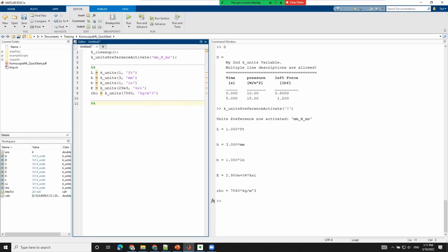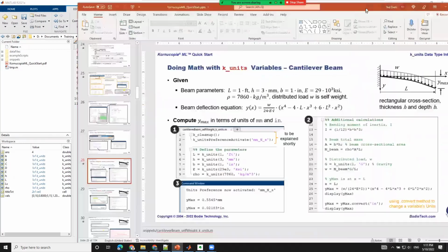So in the formulation of the beam, the first part of the problem, we're going to be defining a weight, and it's divided by EI. So the first thing we're going to calculate is I, and then we'll calculate a cross-sectional area, and we'll use that and the density to get the mass of the beam, and then the mass of the beam divided by its length and also multiplied by gravity to turn it into a weight will allow us to get this parameter W, so we can then ultimately put in the final equation.